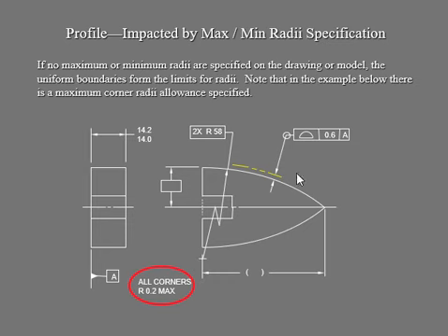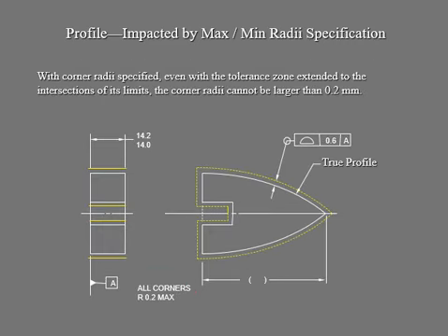So we're gonna pull it in because we have limited space to draw on. We're gonna draw it here with a zigzag line to show that the center is 58 millimeters far away. So that's a big distance. So your corners, all of them, the radius of 0.2 is your maximum. All right, now we're gonna zone it as always. So when you zone it, we can see the true profile right there, in that zone, of course.